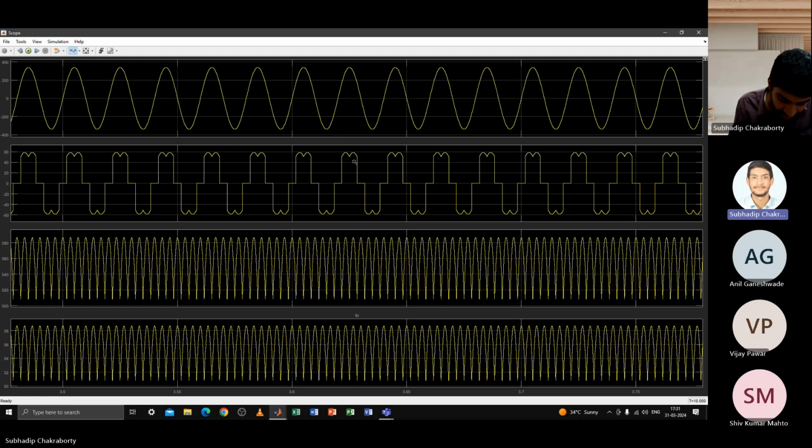But for that harmonic component of the current, there will be no active power transfer. Why? Can you tell? For the harmonic components of currents, there will be no active power consumed or transferred. I told you why it is so. Since the voltage is fundamental and the currents are other harmonics, the average power consumed for the harmonic components, if you integrate sine omega t and sine n omega t, you will find 0. That's why I continuously repeat this statement: there is no active power transfer for harmonic components of the currents, considering voltage is fundamental or voltage is not having any distortion.